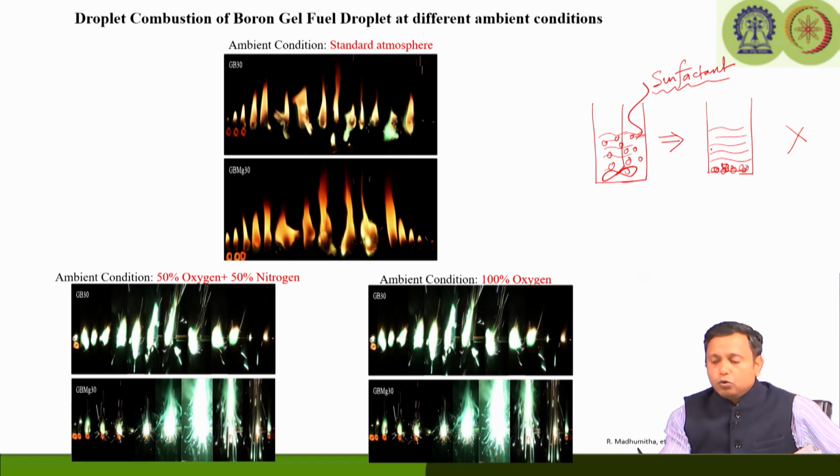So, just with the normal liquid you cannot have it stabilize the particles for a longer period of time. What you can do is either do some modification so that the particles settle down for a longer period of time or do not settle at all. One of the options can be you can make the liquid into gel and hold the particles in that gel matrix, so that the particles are not going to settle down. But now you are making the system more complex, because atomizing the gel will be much more difficult than the liquid fuel. So, that is another problem we are bringing in. We have made the gel, but now how to atomize them properly and burn them properly.